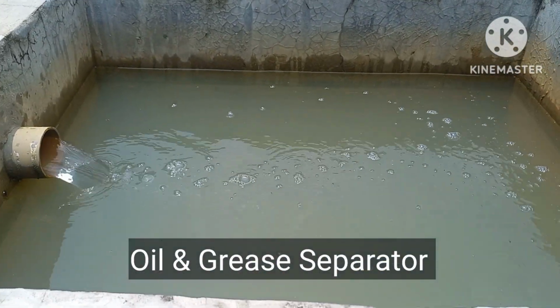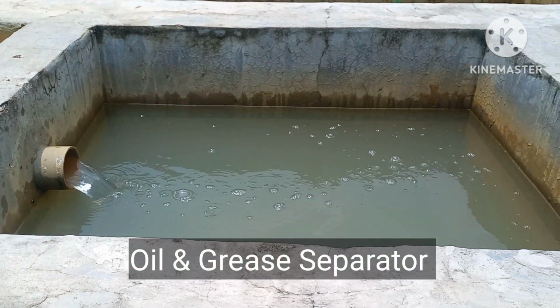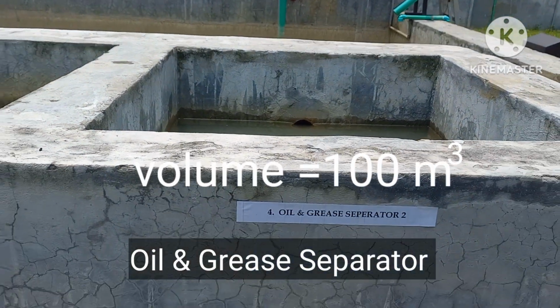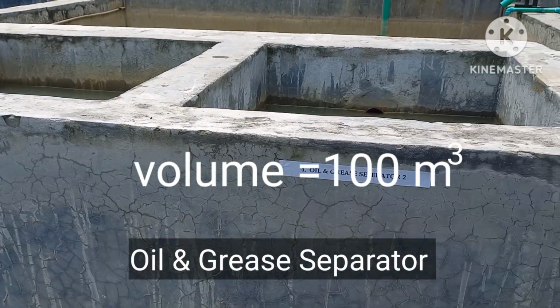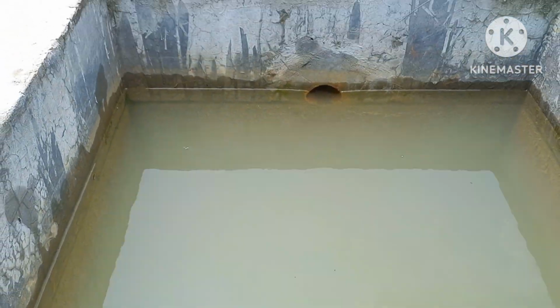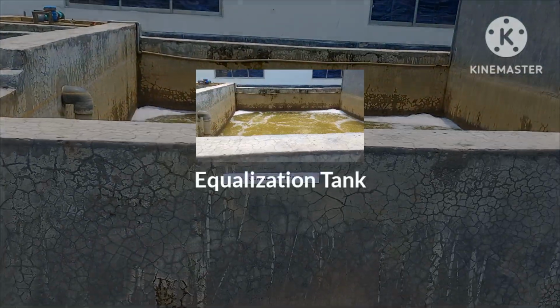After the screen chamber, water will go by gravity to the lifting tank, to the oil and grease separator by pumping. The tank volume is 100 meter cube, that is 1 hour retention time. There are 3 pumps to transfer the water from the lifting tank to the next stage.